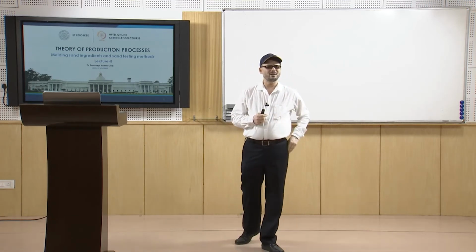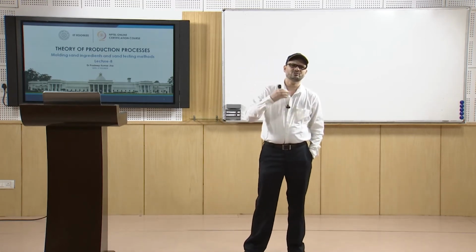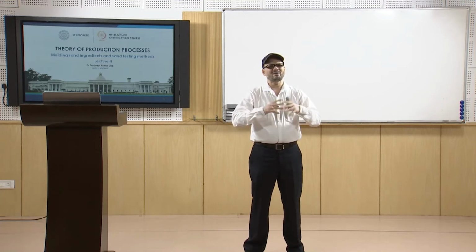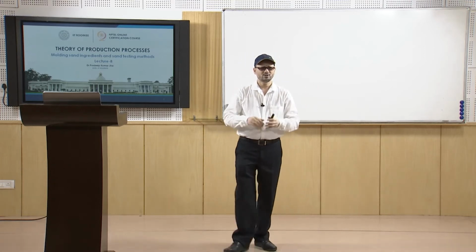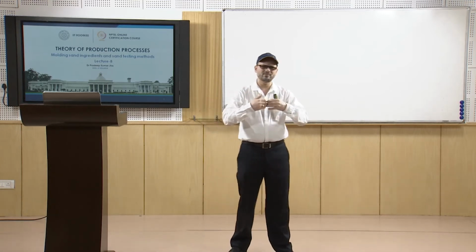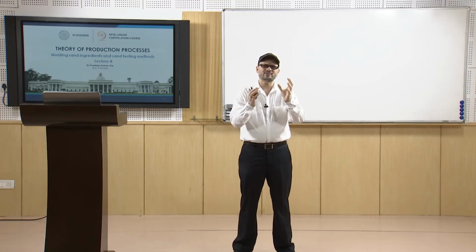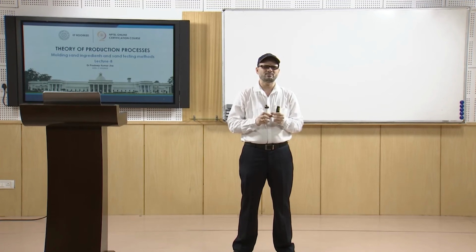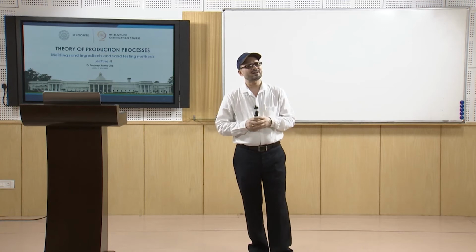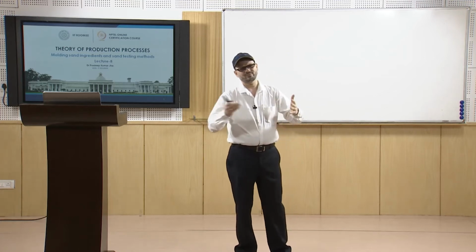So, that is permeability. Collapsibility is the property of the molding material, because once solidification takes place, you have expansion as well as contraction, and after that you have to remove the molding material. So, once you are taking it out, it should be collapsible and come in touch with the casting surface. It will crack, so that you can quickly remove it. If it is not collapsible, if it is not tough, you can say, toughness is different anyway.